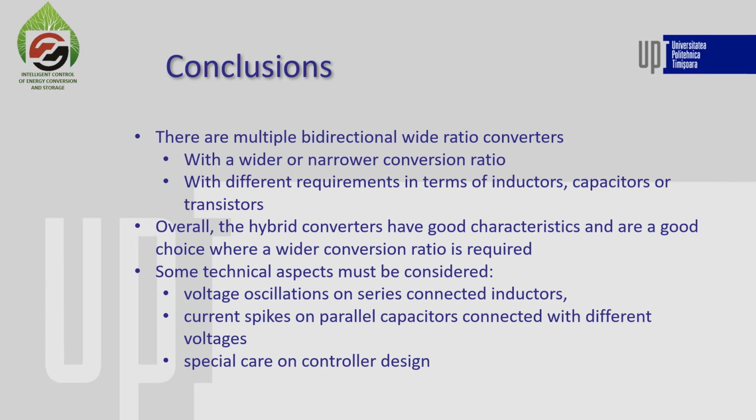Even so, for all converters, important technical aspects must be considered, such as voltage oscillations on series connected inductors, current spikes on parallel capacitors connected at different voltages, or even the controller design procedures if we have a more complex model.